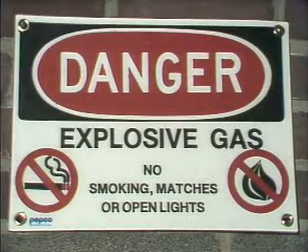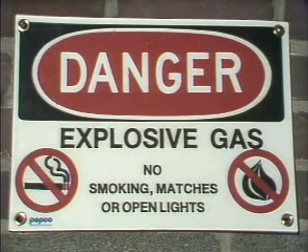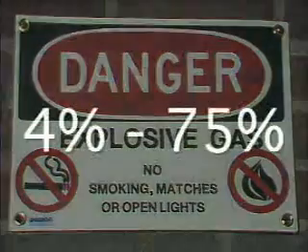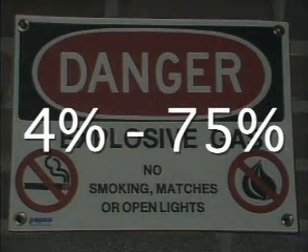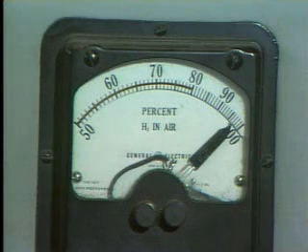One of the problems with hydrogen is that it can explode when it's mixed with air in certain concentrations. The slightest spark can ignite the mixture if it contains from 4% to 75% hydrogen. If there's more than 75% hydrogen in the mixture, however, there's not enough air present to support combustion. So, to maintain optimum efficiency and safety inside a hydrogen-cooled generator, the hydrogen concentration is usually kept above 95%.